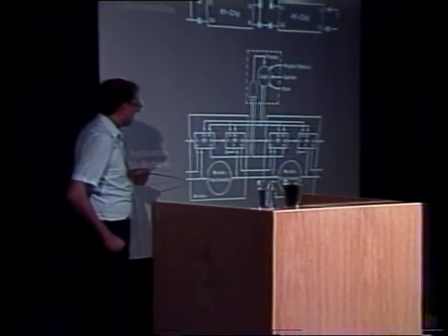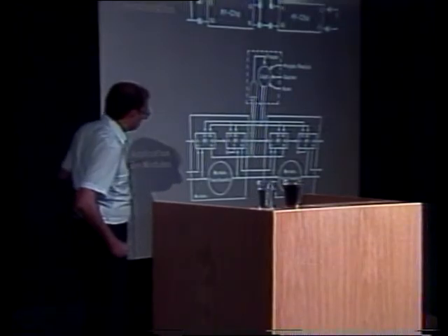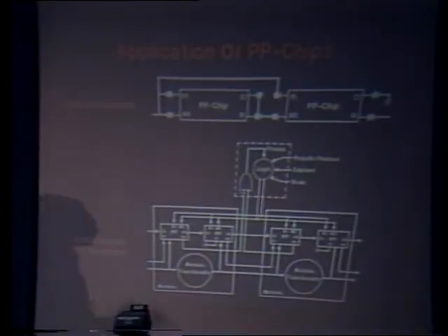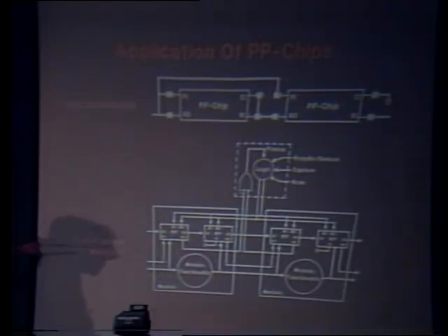Supposing we detect a parity error here, coming from this side somewhere. At that point, what we may want to do is take a snapshot of the data which came in. Okay, so we capture that data which comes in here. It is the syndrome which may be useful for the field service engineer to come later and analyze where the problem came from.